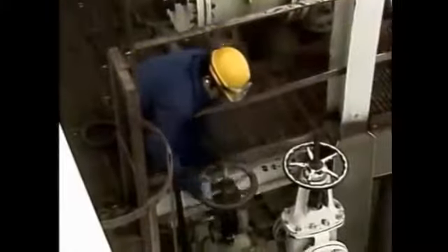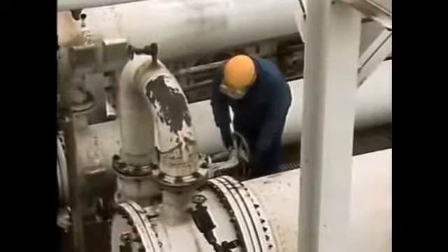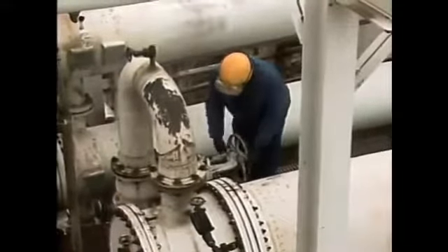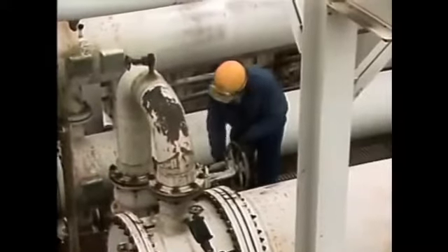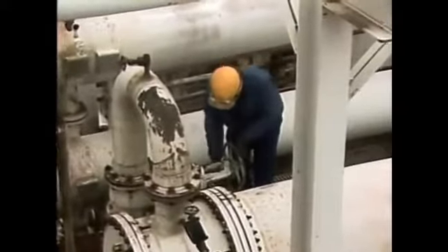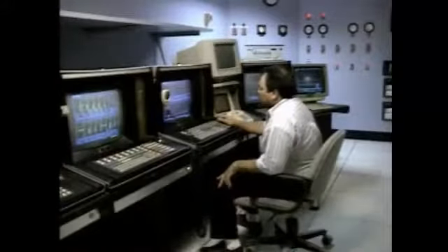With the vent valve shut, the operator fully opens the cooling water inlet valve. The cooling water flow is controlled by the outlet valve, so the operator partially opens the cooling water outlet valve to a predetermined position to establish flow through the condenser. At this point, the control room is contacted and the process can be started.